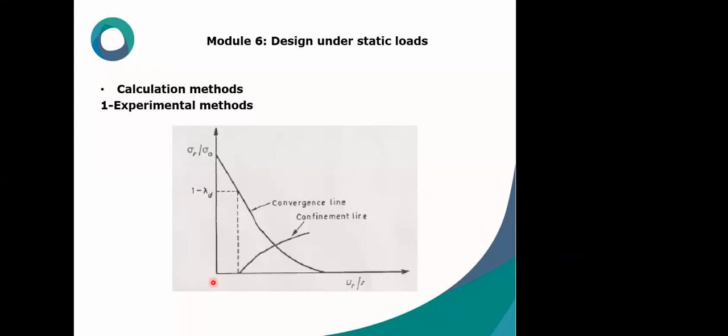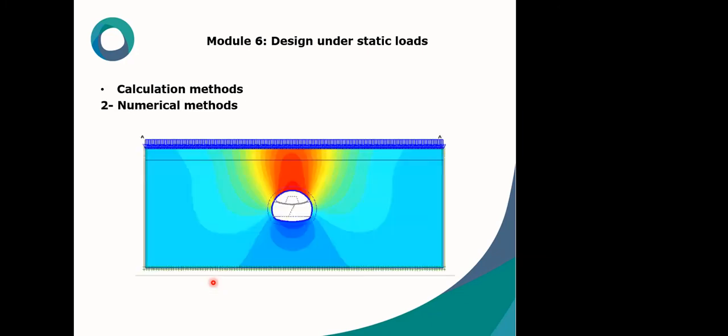In order to simulate the excavation stages, which are in fact a 3D physical issue, the numerical model uses the stress release ratio. So here we have a 3D problem, which is the construction stages in the NATM tunnel, and we wanted to use a 2D model. So the concept of a relaxation factor or release ratio is generated here in numerical modeling.